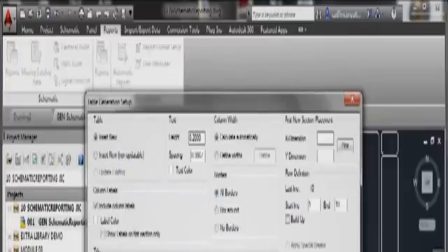And then we've got all our settings for things like text heights, spacings, insert new. We can insert a new non-updatable table. So this is coming in as an AutoCAD table. If you set it as non-updatable, it's a one-off snapshot of your project. If you do insert new, it means it's updatable and can be updated at any time. Title, I'll include the time and the date, include the project info, and include the title line.